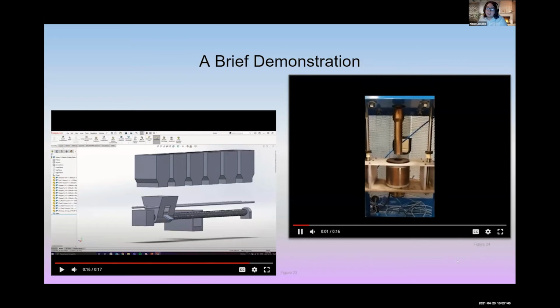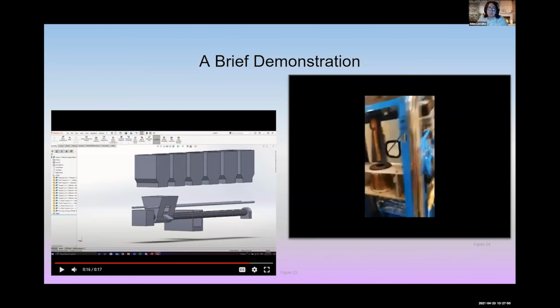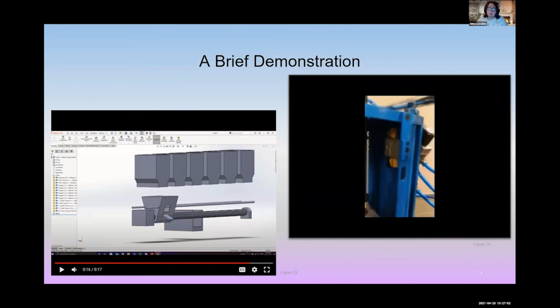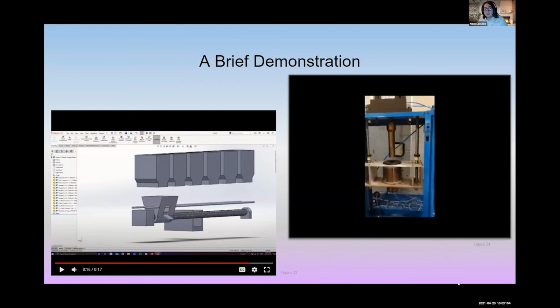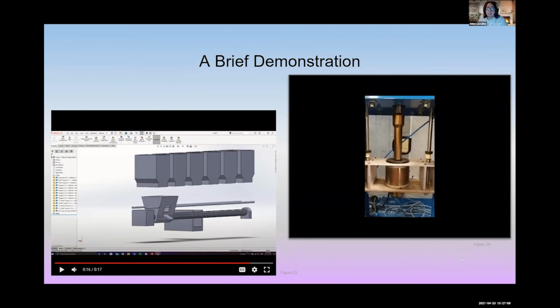Our second video is demonstrating the operation of our pneumatics to drop the piston and raise it, as I mentioned before. This process is being controlled through the PLC using a piece of test code we made up to run in a loop. The PLC opens the safety valve, allowing for air to leave the annulus area, which is the bottom side of the piston, and filling the cap end, the top side of the piston, causing it to lower.